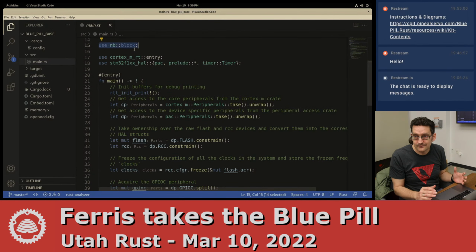And those are what have the SysTick timer. So any ARM Cortex CPU in any microcontroller that uses that CPU will have the same SysTick peripheral. All of the things like how GPIOs work and all that, those vary a lot between different manufacturers and sometimes between different lines of those manufacturers, but the core peripherals like SysTick remain the same.